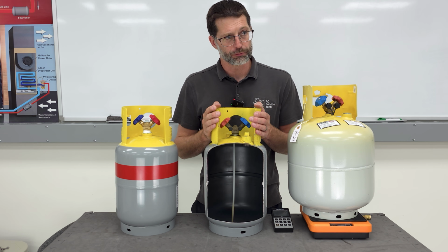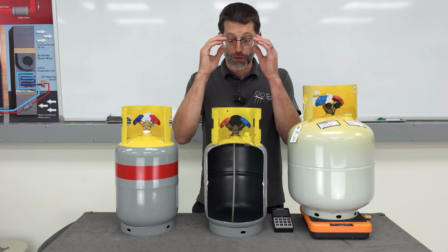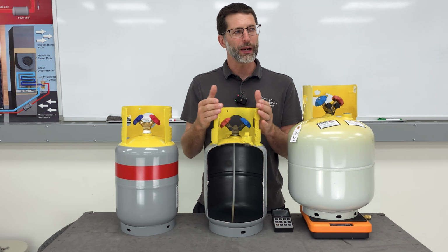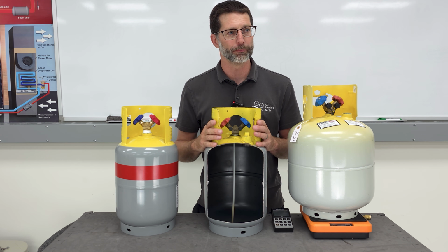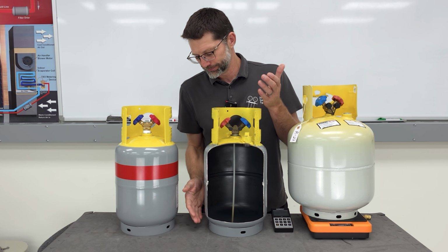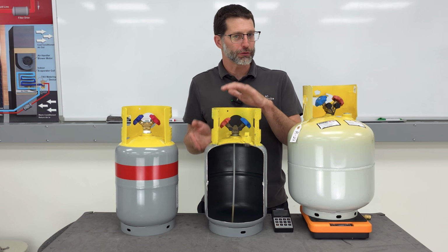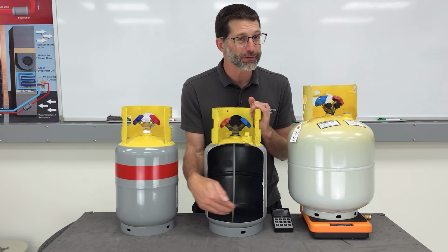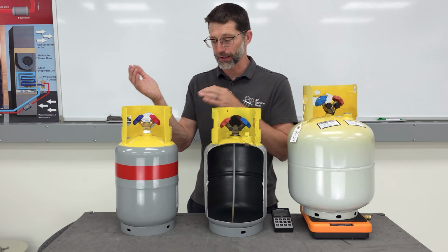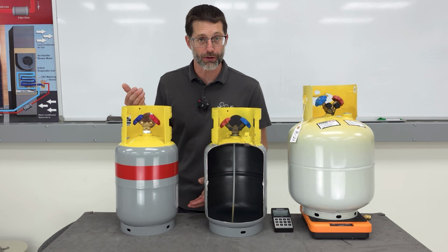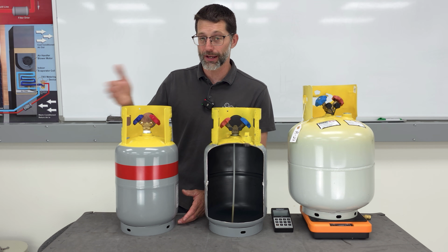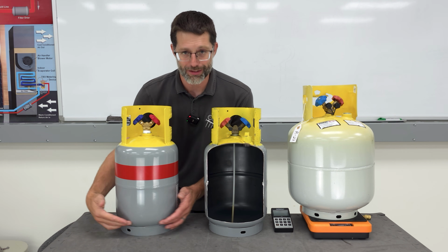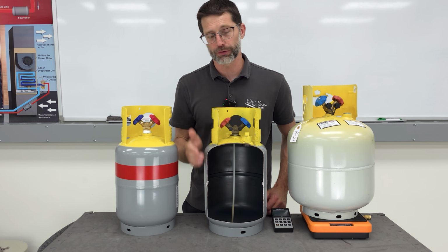If you were recovering refrigerant out of a single system and you wanted to reuse that refrigerant, you could reuse the refrigerant, but I wouldn't advise necessarily reusing refrigerant out of a used bottle, because at the distributor, they don't clean the inside of the bottles. So you have old oil from compressor burnouts and stuff like that in these tanks. When you get a tank that's empty from a distributor, it doesn't mean it's new. It's just a used tank that somebody else has exchanged, but now it's empty. And so you could have these contaminants in the bottom. You don't want to charge that back into a new system again.